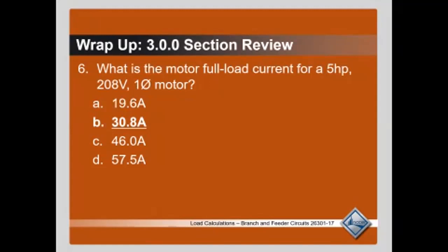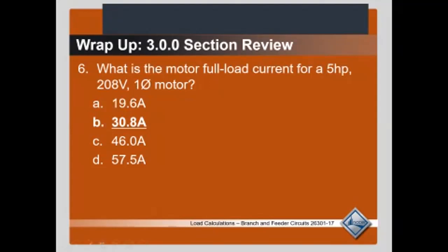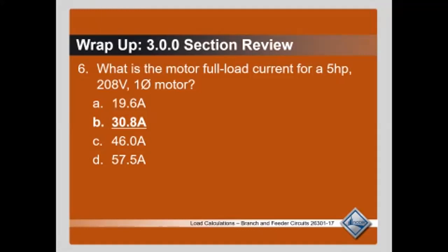So if we look in section 3.6.0 under motor loads, it says look in table 430-248 in the code book for single phase motors. 430-248. Table 248, there we go.